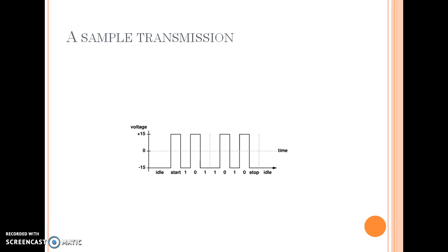And this is an example of a serial communication. Here we are sending data byte 10111010. First we are sending the start bit, and the start bit indicates the beginning of the word, and then the data bits. Data bits is the data that the user is transmitting. These are the data bits. And parity bit. Parity bit is an optional bit. Sometimes we can use it, it depends on the user if he wants to use the parity bit. And parity bit checks the integrity of data. And this is the stop bit. Stop bit indicates the end of the word.